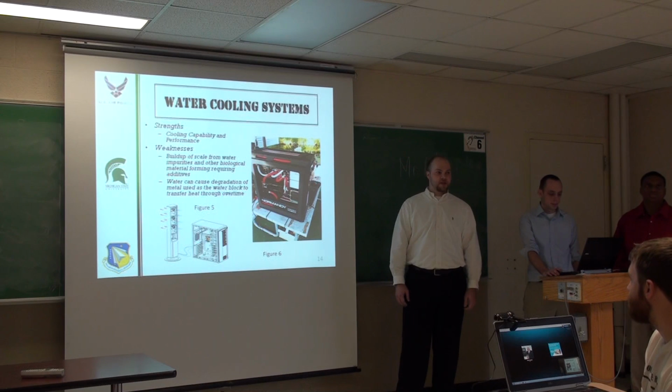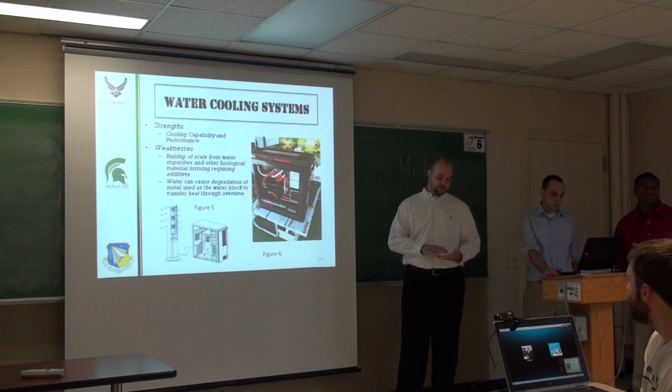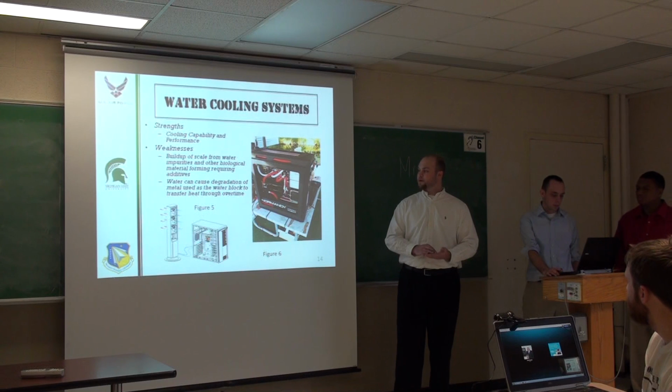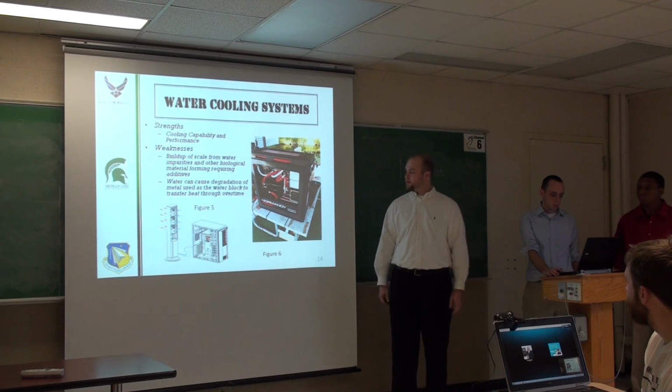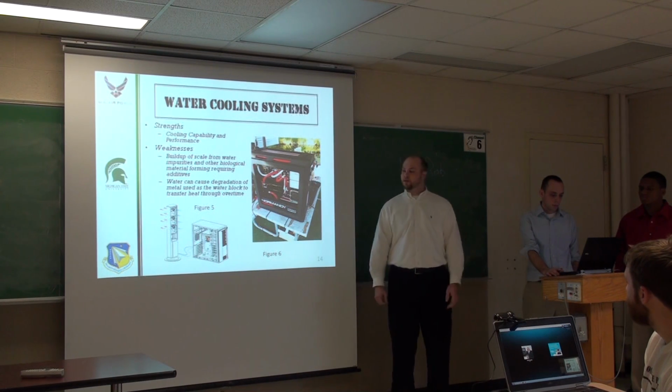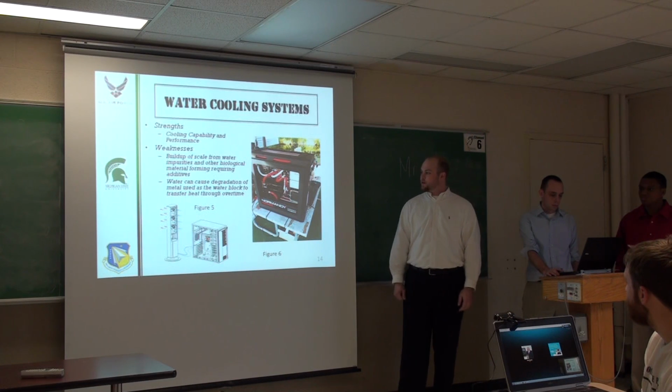Also, water can cause degradation of the actual water blocks. When the water block sits in between your heat source and the water that flows across the other side, they'll slowly start to degrade the metal and create metal particles in your system, which can be bad for your pump over time. So once again, you need to essentially clean out your reservoir.